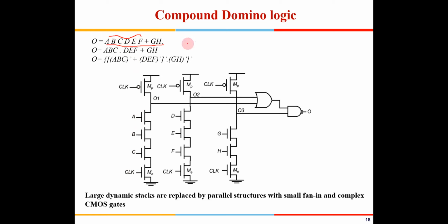So in those cases you can split the circuit, okay? Like if you can write this as it into 2 out here, right? And then you can do this algebraic manipulation. So you have ABC bar plus ABC bar, the whole bar, right? By De Morgan's theorem, when it comes, it will become the same thing, right? And then again you are putting a bar out here and a bar out here, and this OR now becomes an AND, because you have put this bar outside here, and then you have put one more inverting option out here.